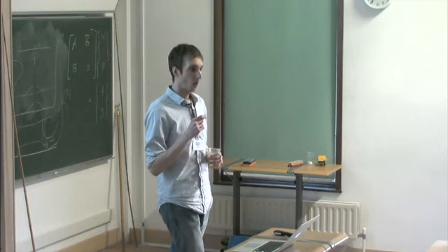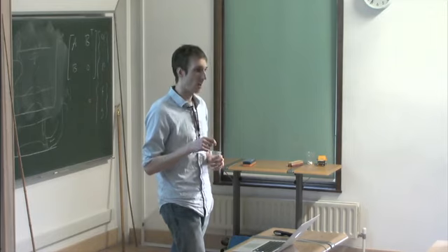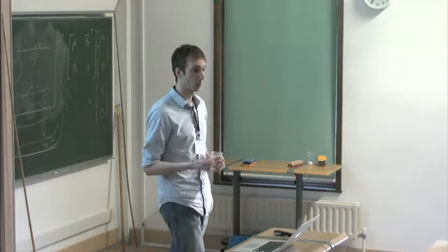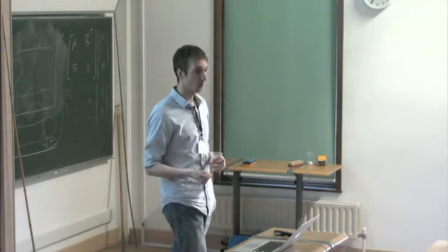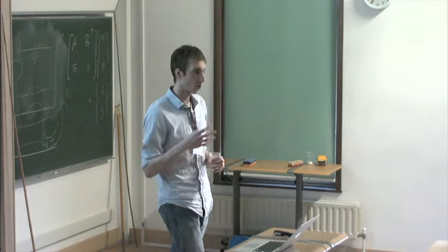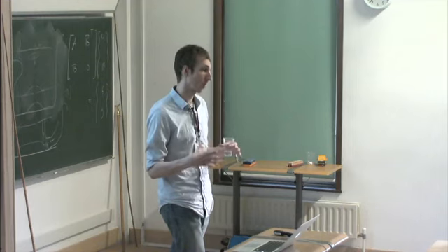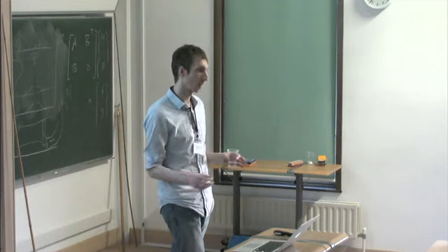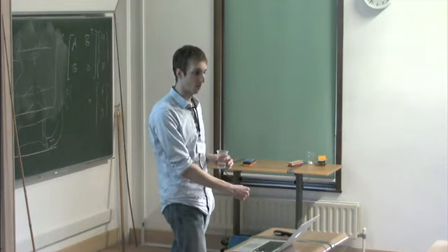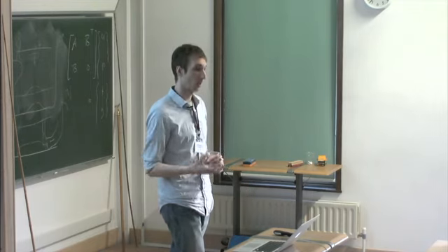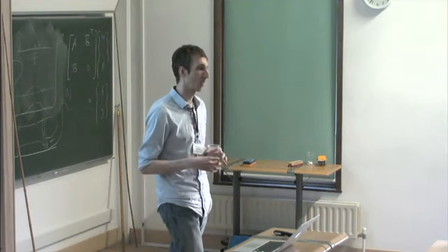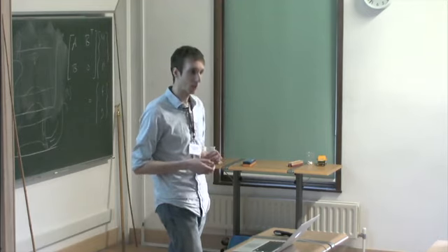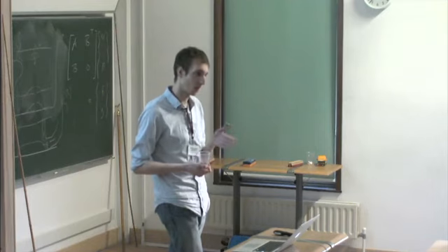And so when you look at this dimensionless parameter for drying, what we see is that effectively large spheres are closer to free drying than small spheres. And so as a result, it shouldn't be unexpected that large spheres will have a much larger tensile stress on the outside. And in fact, when I bought a whole bunch of these spheres initially, they come in a wide variety of sizes, from less than a millimeter up to a couple centimeters. And the ones that are a couple centimeters swell to a size that's, I'd say, 10 centimeters or something like that. And I don't have any of those left because they all cracked when I was drying them. So it absolutely does develop a large tensile stress on the outside. And if you exceed a threshold, then they start to break.